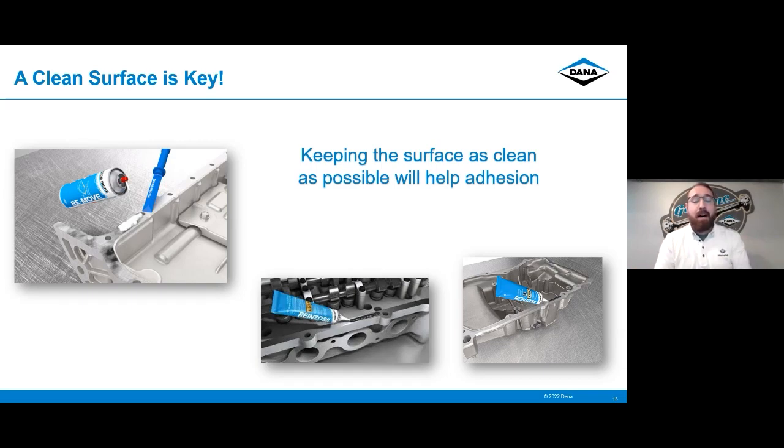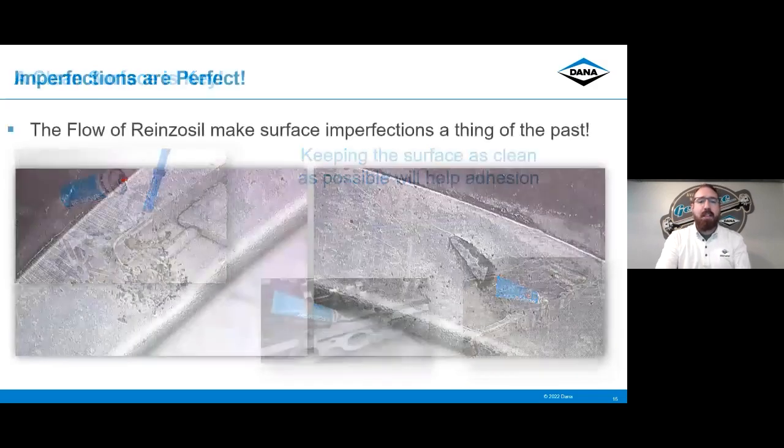And believe me, I think we've all seen a valve cover come off completely covered in oil, covered in dirt, covered from any type of dust. And if you don't get that cleaned off, you're not going to be happy with the results. So just keep that in mind whenever you're installing any type of silicone sealant.